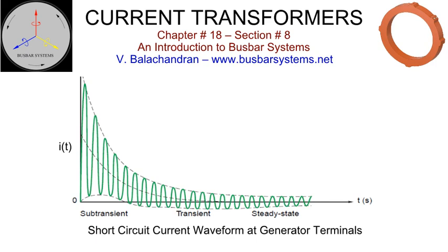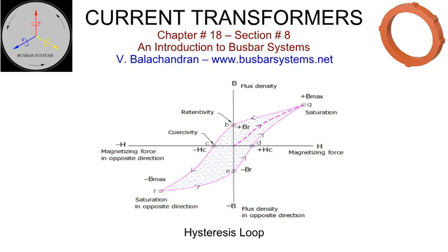It is advisable to cast each core separately. Since the fault levels are very high in a generator connection, a severe fault current with a high DC component can permanently magnetize the core. This is referred to as remnant magnetization or residual magnetism. Its effect is to shift the bias along the BH curve. The phenomena could lead to significant variation in the magnetic parameters that were assigned at the time of manufacture. These variations are observed when testing a current transformer for its short circuit withstand capability.